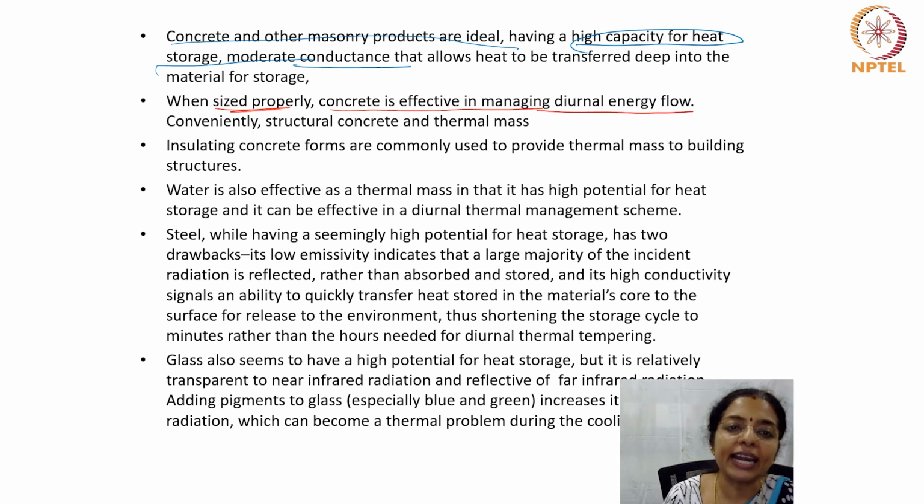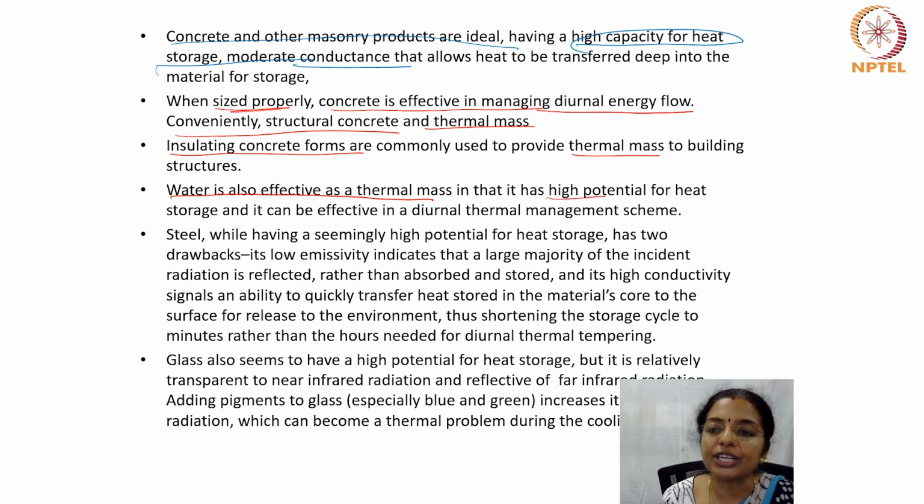It is also convenient to have structural concrete as it has thermal mass. Insulating concrete forms are commonly used to provide thermal mass to building structures. Water is also an effective thermal mass in that it has high potential for heat storage and it can be effective in a diurnal thermal management scheme.